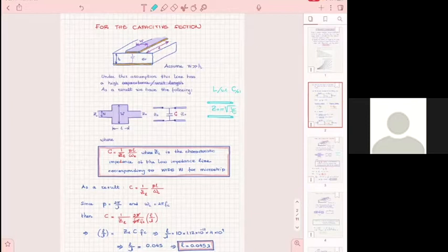And do you remember what we said? That a line that has low characteristic impedance normally has what, in terms of L and C per unit length? I said low characteristic impedance means high capacitance, because C is in the denominator, inside the square root.